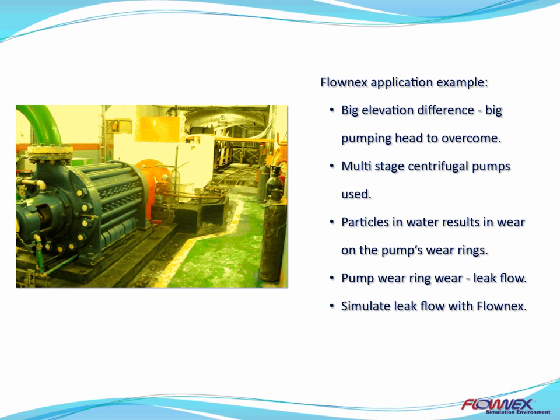Due to the big pumping head, multi-stage centrifugal pumps are used. These pumps have wear rings in between stages to prevent recirculation of water around the impeller. Due to particles in the water, the wear rings wear, resulting in increased leak flow. Flonex can be used to simulate the pump including its leak flow, thus determining the derated performance of the pump.